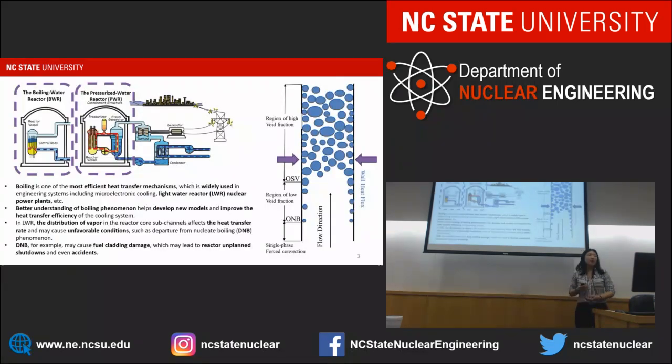So first, thermohydraulics calculation is an essential part of nuclear engineering. In light water reactors, of course, water is the heat transfer medium to remove heat from the core. Boiling, among all kinds of heat transfer mechanisms, accumulates large heat flux with relatively small temperature difference, which makes it ideal for applications which require substantial heat transfer rates, like light water reactors.